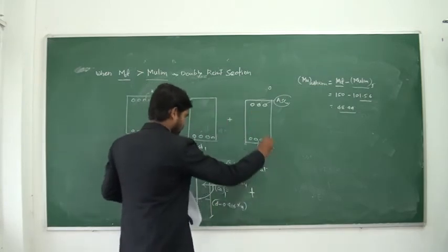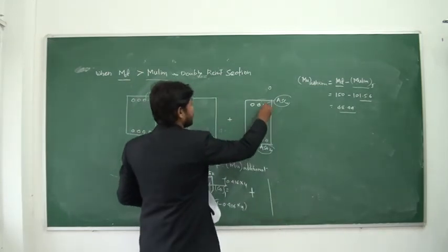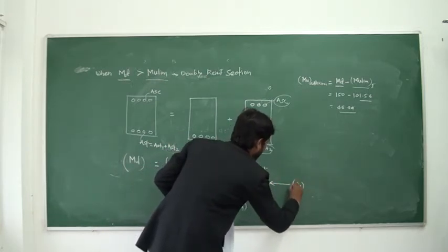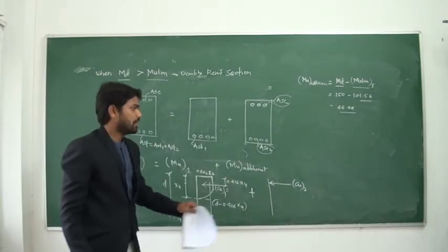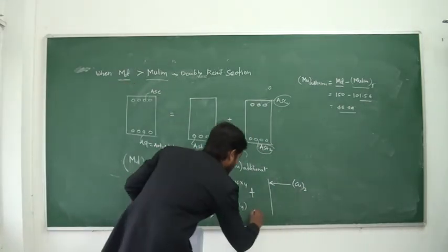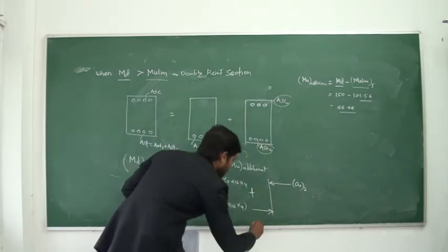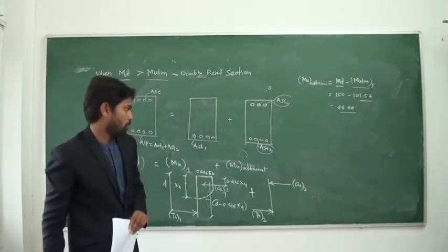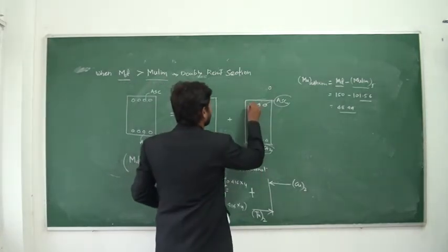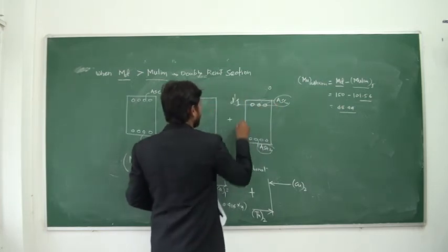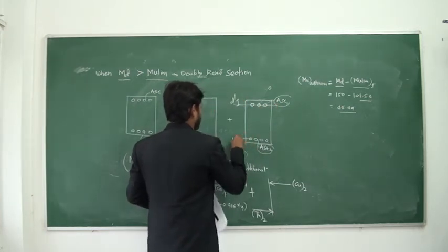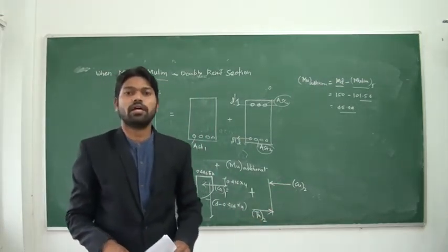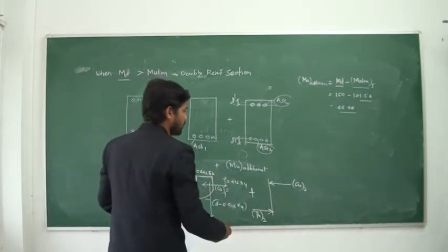Now if you draw the stress block diagram for this case, this ASC will generate a compression Cu2, developed by the steel, and this AST2 will develop the tension Tu2. Now this reinforcement will be provided at an effective cover d dash. Both the forces Cu2 and Tu2 are equal and opposite, so they will form a couple.